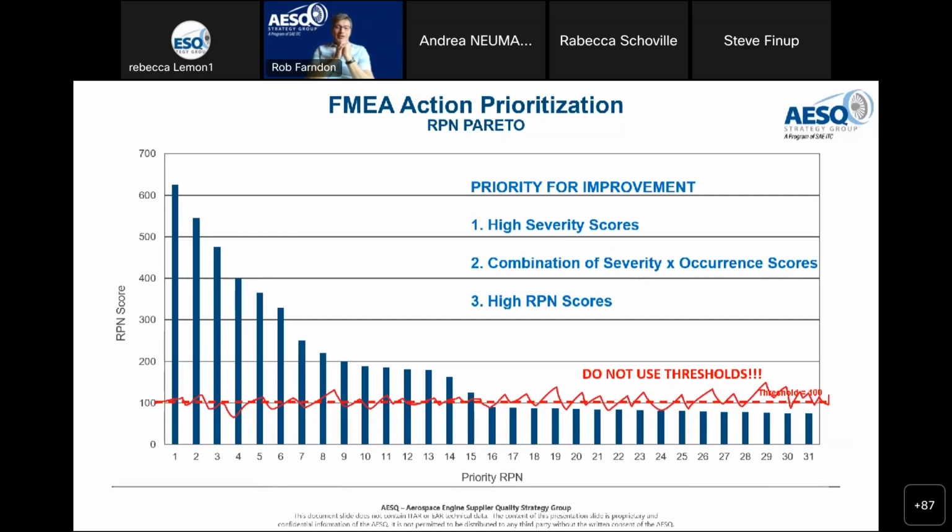A question in the chat is about designing out. What I'm looking for, really, is a principle of as low as reasonably practicable. Certainly where I have a safety-based failure mode with a 10 in severity, or even for some of the functional failures, primary and secondary function, I always ask myself what I can reasonably do to improve that score. If it's a fairly easy activity to do, I will go do it. By that, you nibble away at the scores. They come down and down and down.